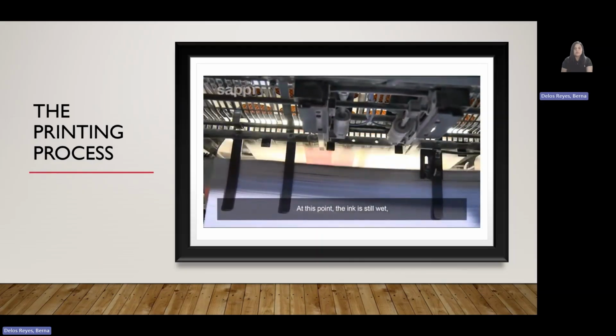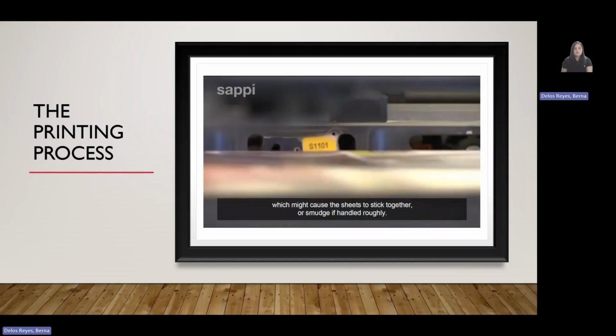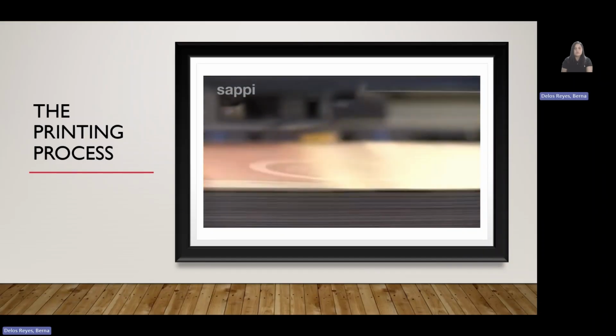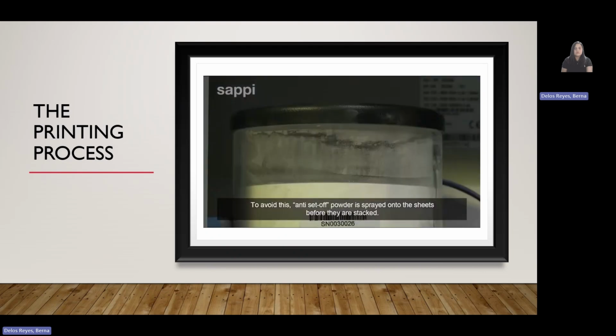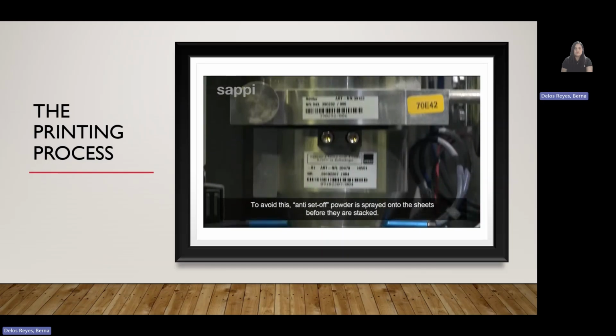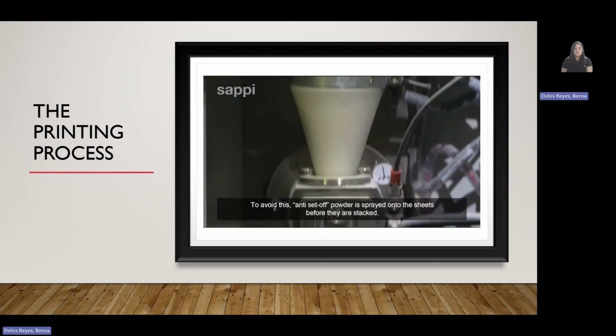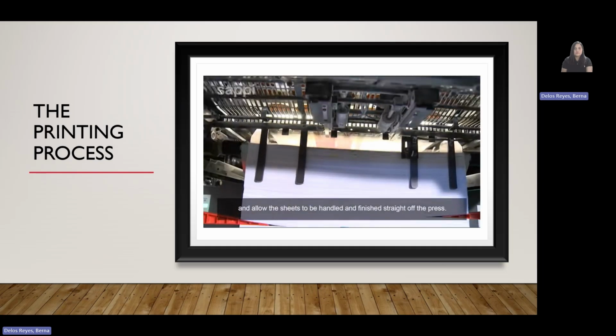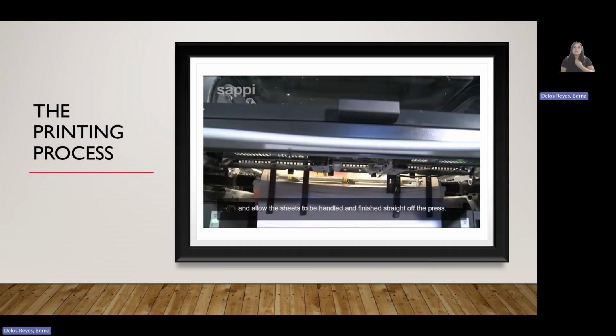At this point, the ink is still wet, which might cause the sheets to stick together or smudge if handled roughly. To avoid this, anti-set-off powder is sprayed onto the sheets before they are stacked. Specially formulated rapid set inks and papers use less anti-set-off powder and allow the sheets to be handled and finished straight off the press.